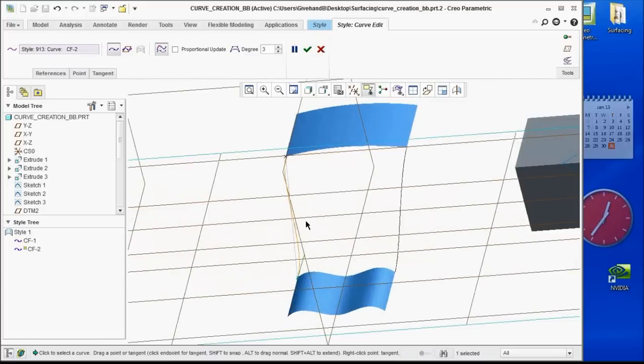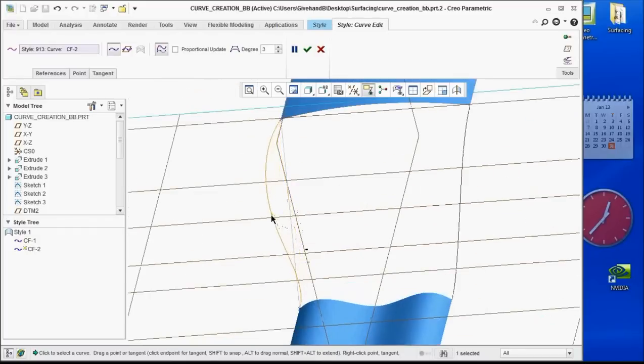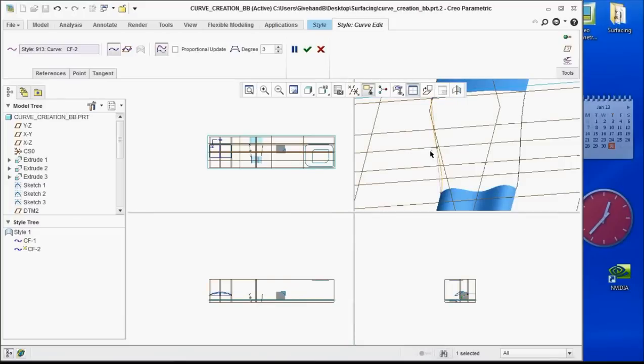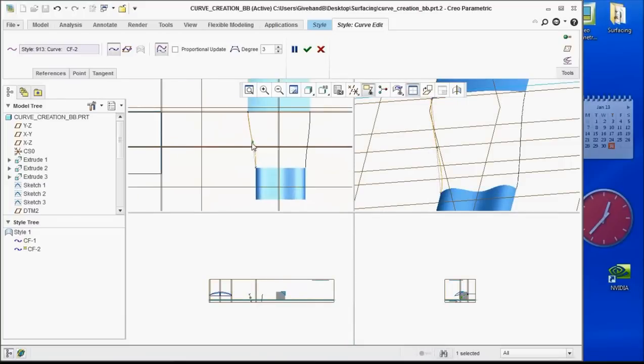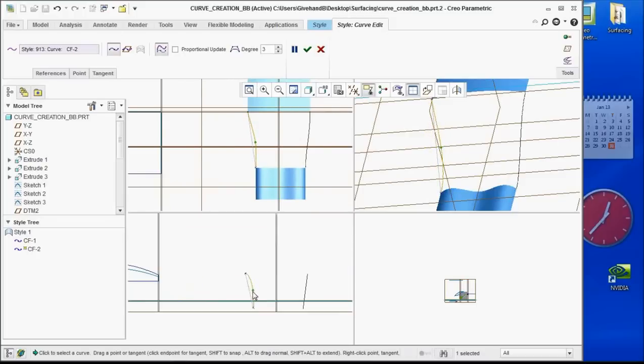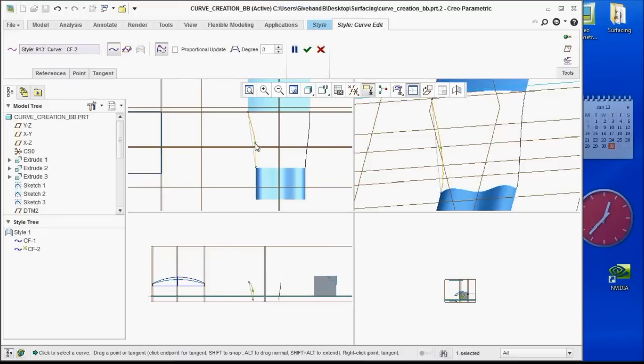Right. Now, also, one thing while we're on this side, okay, if I come in here, I can right-click on this curve and say I want to add a point, or in this case, a midpoint. And now, as I drag, you can see I drag this curve quite a bit differently from this point. Also, what's really unique about the ISDX tool is that if I pick the 4 views, notice how now I can manipulate it, but only in the appropriate view. So notice how I drag this out. At this point in time, I'm only dragging back and forth right here. You can see it move from essentially a front view back and forth, but where you don't see it move is from the side view, okay?